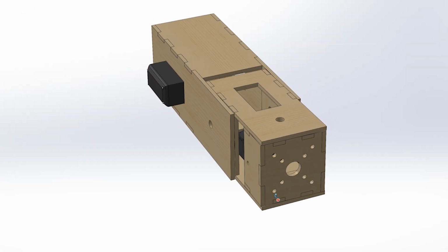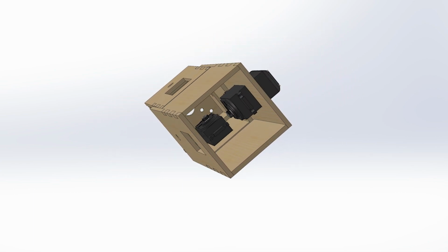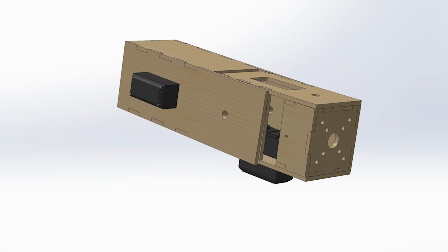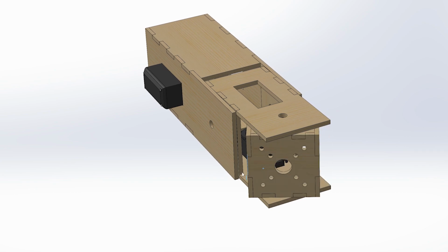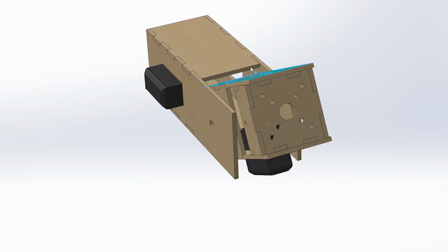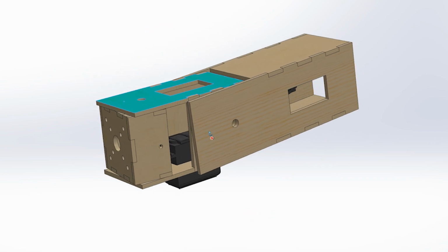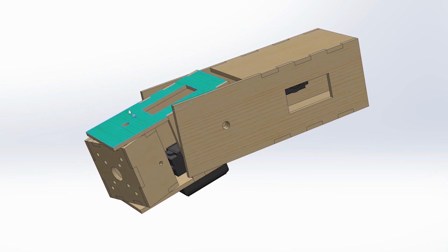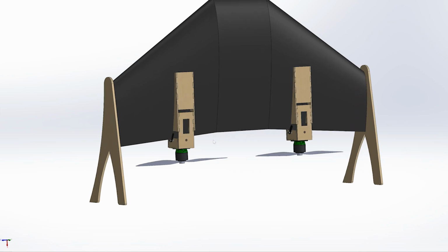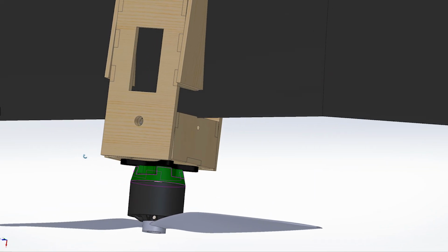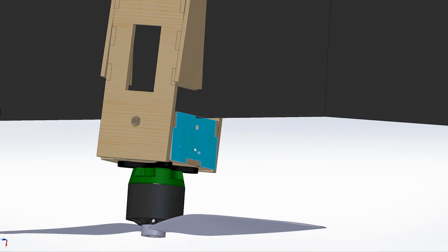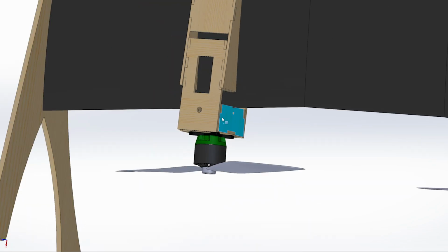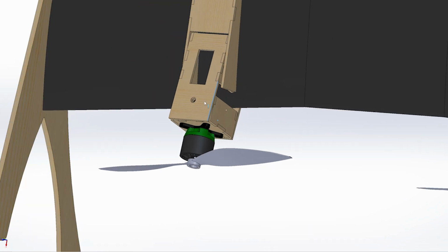For the thrust vectoring mechanisms, I wanted to keep them as simple as possible to reduce parts count and aid with assembly. Each axis is controlled with its own independent servo and has linkages to push and pull each side to add more even loading. An important aspect of the design was to find a happy medium between deflection and resolution, to allow for reliable control while also being able to deflect wide angles for large maneuvers.